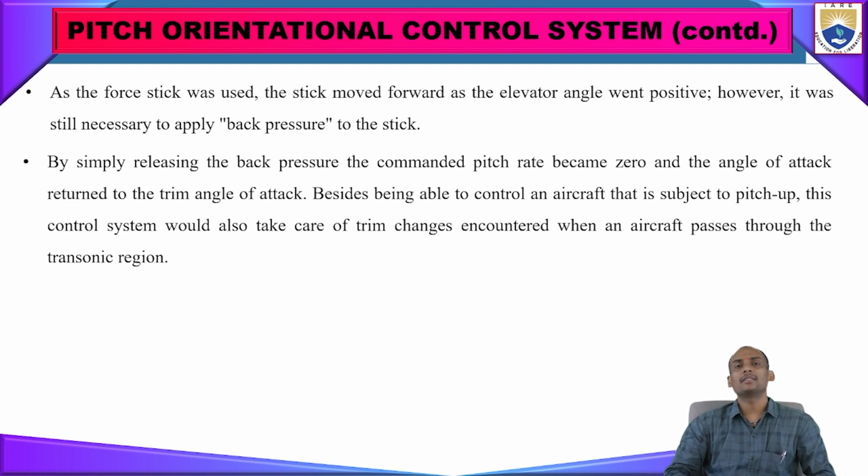In the pitch orientation system, the design of the control system mostly depends upon the angle of attack of the aircraft, and whenever it makes the transition from the subsonic zone to the transonic zone, how high angles of attack give stability variations for the aircraft, whether those variations are felt by the pilot or not, and what conditions are required for the pilot to feel that force also need to be designed, by installing two rate gyro sensitivity sensors in the block diagram, and the root locus behavior we have also shown here.